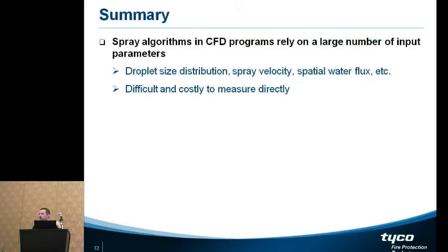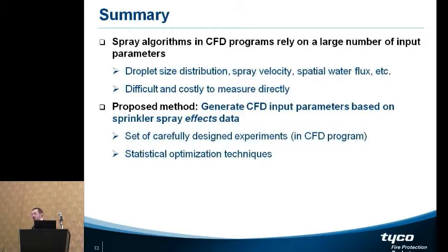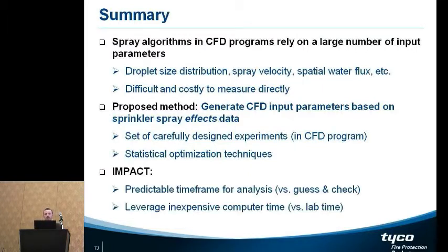In 2 weeks' time, we were able to actually create the sprinkler and had something we can use for the analysis. So, just to summarize, we know the spray algorithms and CFD programs rely on a large number of input parameters that you have to go out and measure using these complicated techniques. And there isn't a lot of published data out there that you can use, but there is some that you can use to kind of guide this type of analysis. Instead, if you have access to some performance data, you can set up this carefully designed set of simulations and extract those optimum parameters using this optimization technique. And the impact of that for us was a predictable time frame for the analysis.